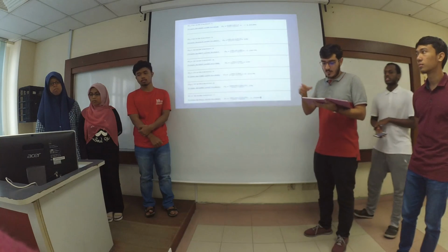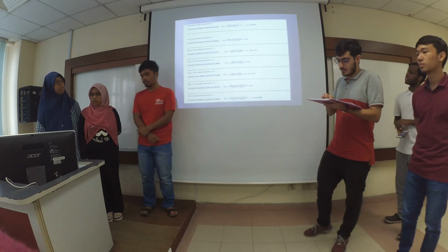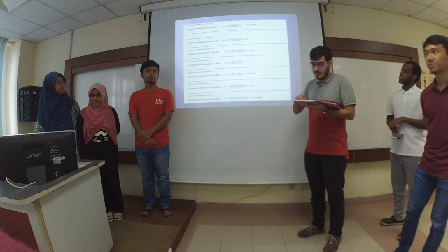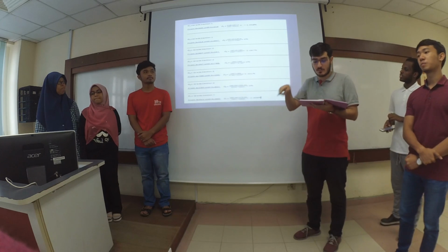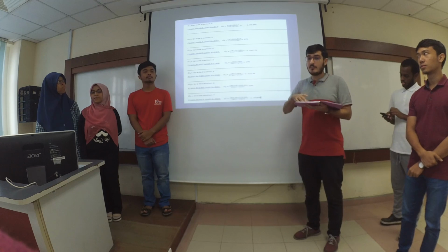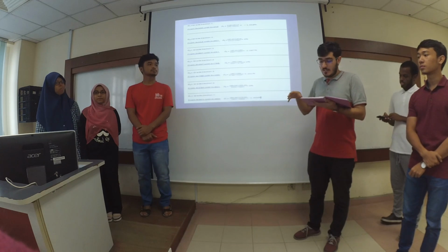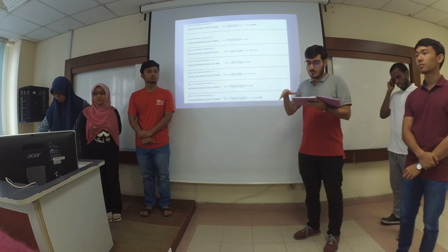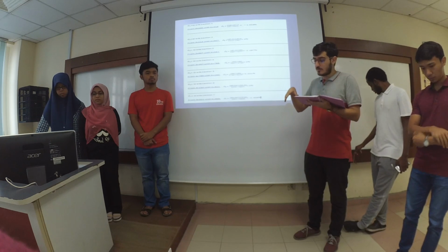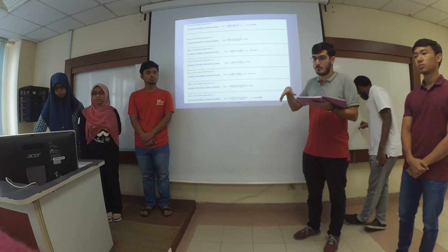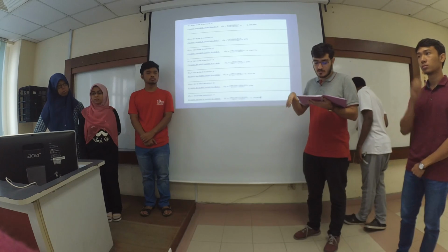So first, I want to explain the stages of our design. Firstly, we designed the cross-section elements and their dimensions for the bridge and the roadway. Secondly, the vertical alignment was designed, and it was ensured that all grade lines along the vertical alignment for our proposed roadway are below 2.1%, which was referred to the standard.